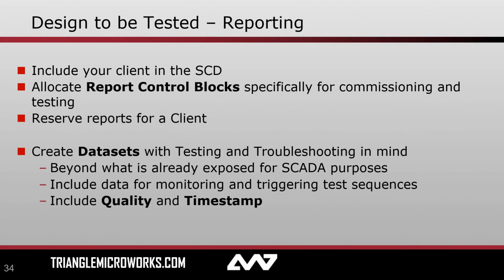That means that you can ask that vendor for an ICD file, which describes the capabilities of that device, and then include it into your SCD file, your system configuration description. Once you do that, you are able to allocate report control blocks specifically for that client.